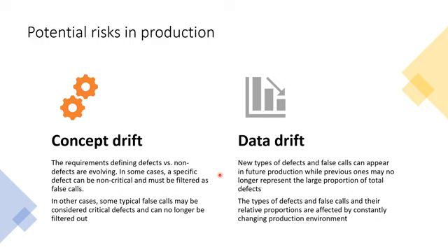An example could be a foreign material that is stuck on a trace. When it can be removed, then it's a false call. But if it cannot be removed, it stays on the PCB board and it becomes actually a critical defect. So those kinds of concepts keep changing.